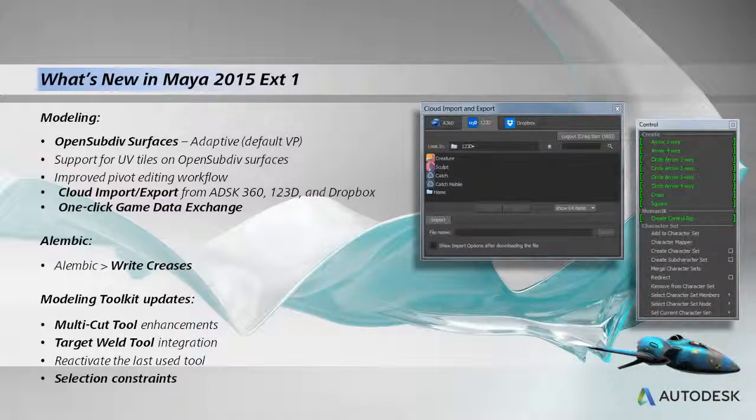Within the modeling world here, improved pivot editing workflow. So this is really nice. This is where you can actually customize your pivots to just about anything else. So you can take an object, and grab a component from another object for that matter, and use that to drive your pivot. And you can do this on the fly as you model and work on any object now within Maya.